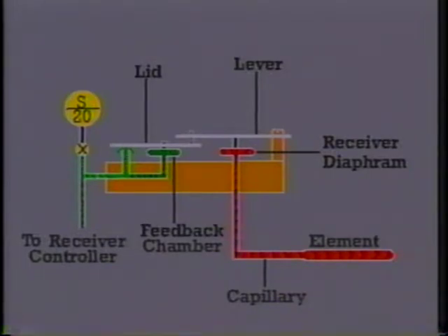Once the proper transmission pressure is reached, that constant pressure is trapped in the transmission line, and the only airflow path is between the restrictor and the control port. The restrictor is needed here to reduce the volume of air so that the exhaust rate is manageable by the small control port and lid.